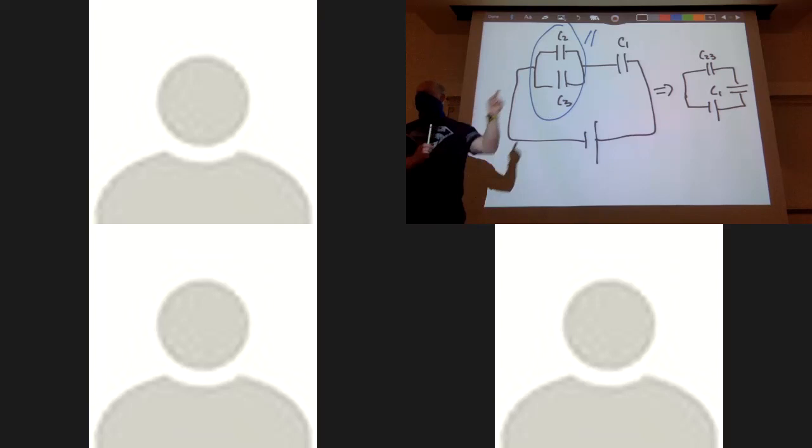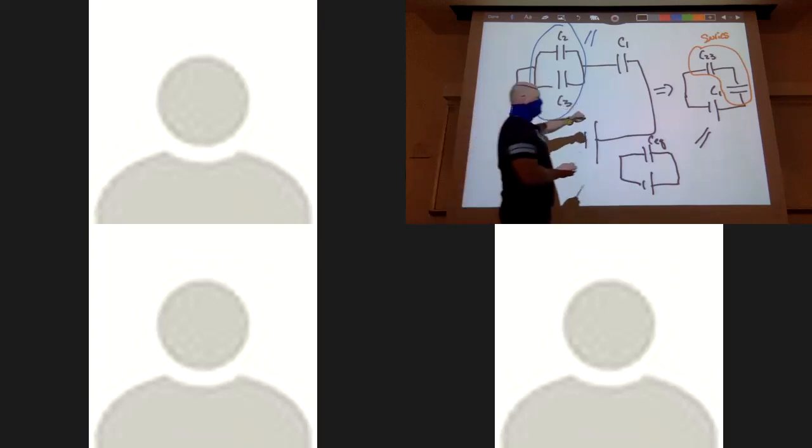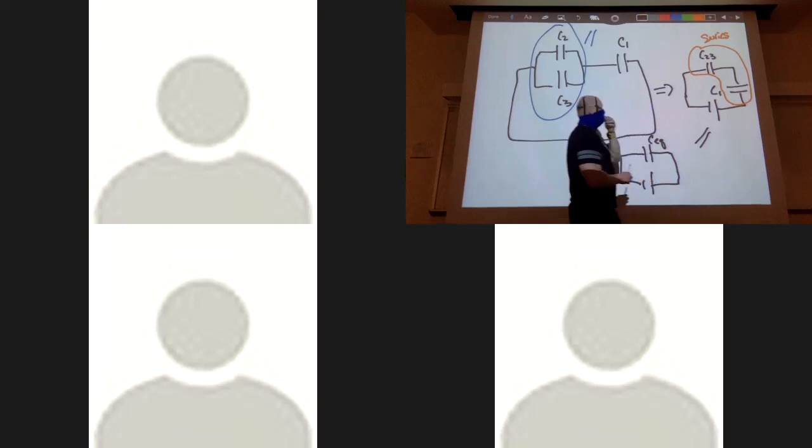Okay, good. So how are C23 and C1 connected to each other? Is there an option for the charge to go anywhere? No, it has one particular way it can go, which means that these two are connected in series. So here, we're going to combine these two together to make our final, which is then CEQ. Again, we're going to do this in steps, and you'll see why tomorrow, why I really want to do these things in steps. So now we can start collapsing these things together.